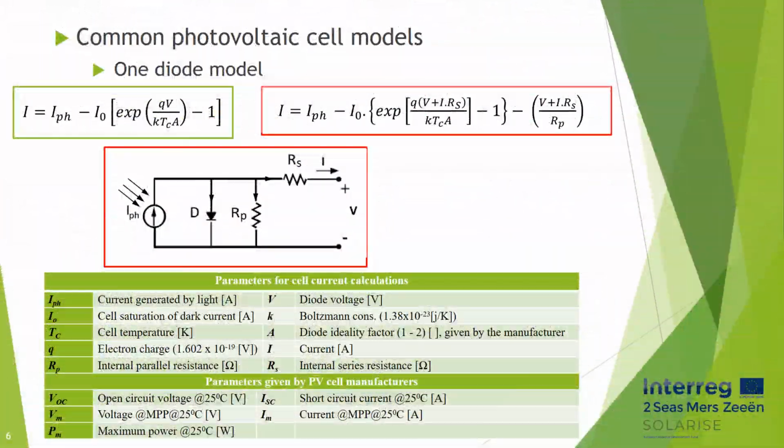To understand the one-diode model, we can go into details. Firstly, we know that the cell is a constant current source formed with a semiconductor structure and the generated current increases with light. We can define the current generated by light as IPH and the current can be used as I. Since the structure is a semiconductor structure, there should be a saturation current like in the diode equation.